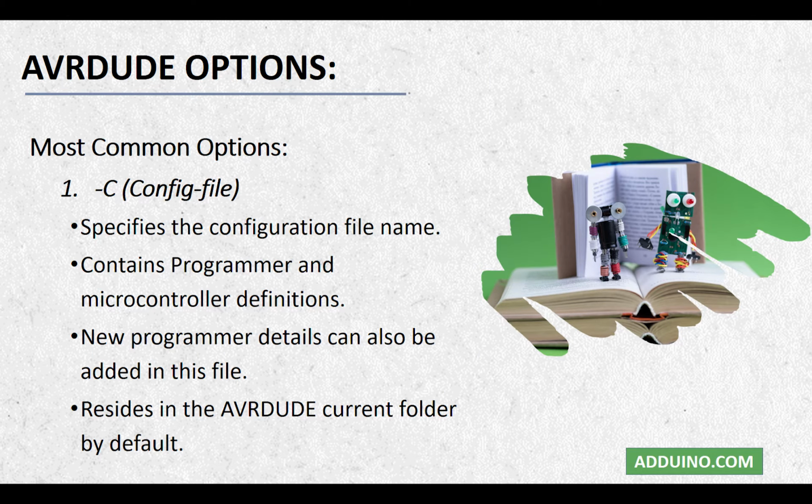Now let's discuss the different options of AVRDUDE. AVRDUDE provides you many options and functionalities, which can be listed in the command line. Let's discuss the options that are most commonly used. You should note that these options are case sensitive.